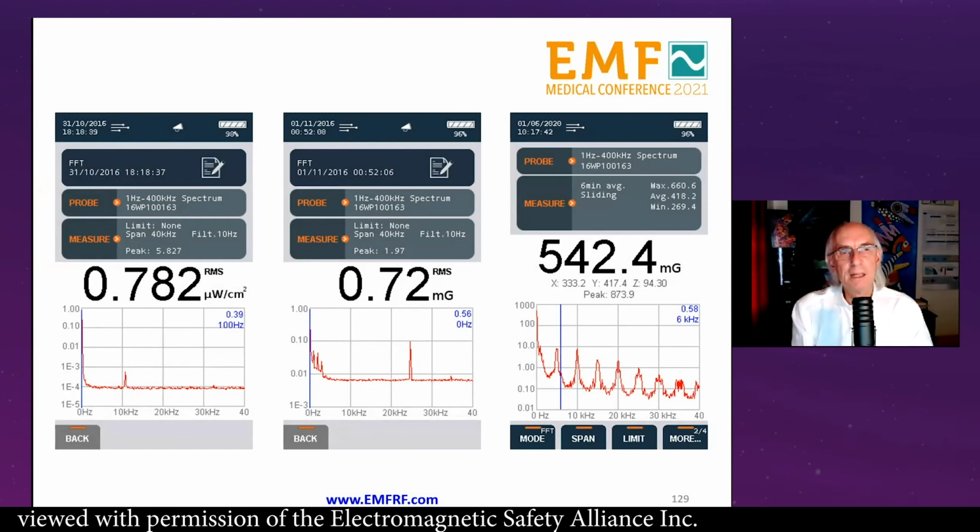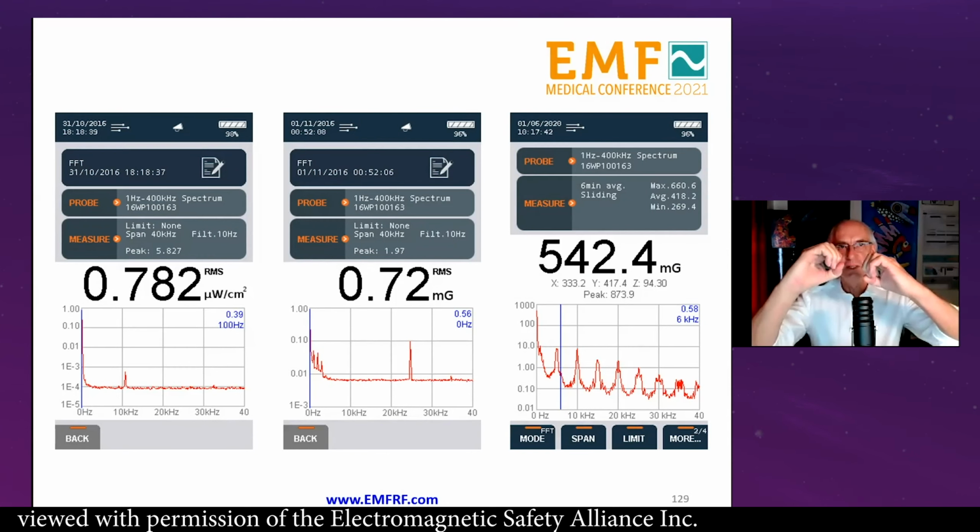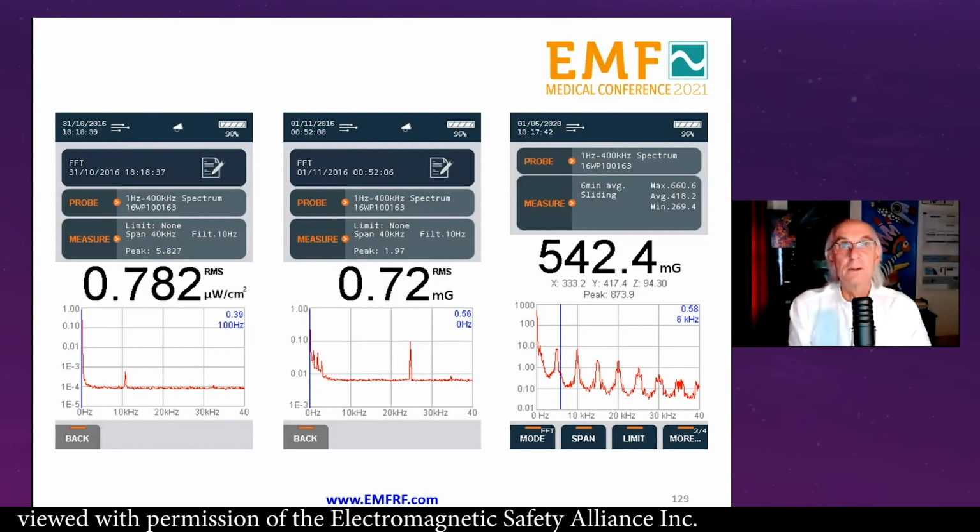Well, anytime you convert the voltage. In the old days, we used to have transformers, one transformer for 120, and then we convert that down to, let's say, 12 volts with magnets and wires. That has gone away. Those were the big bricks we used to carry around with our laptop computer. Nowadays, that's done electronically. And when they do that electronically, they distort the signal, and then we get many of the other peaks coming up. What are some of the culprits who are doing that?